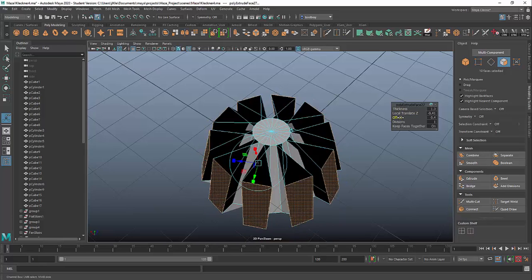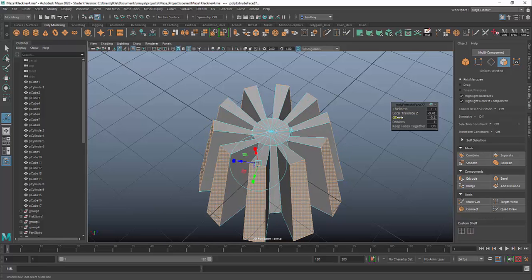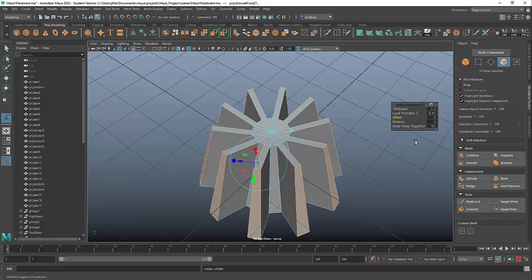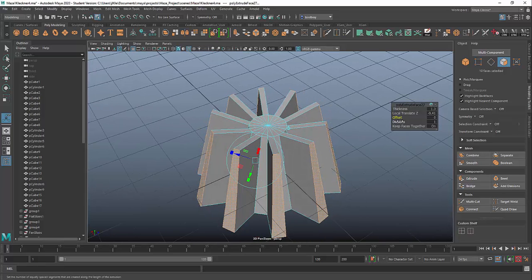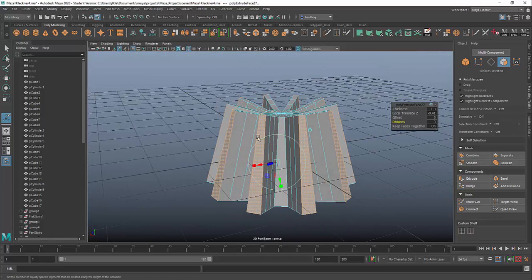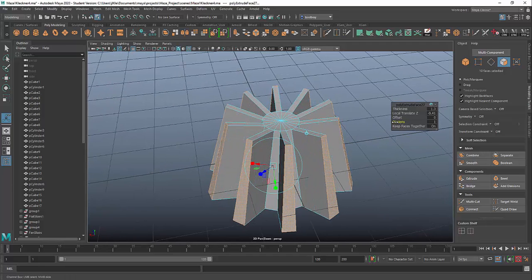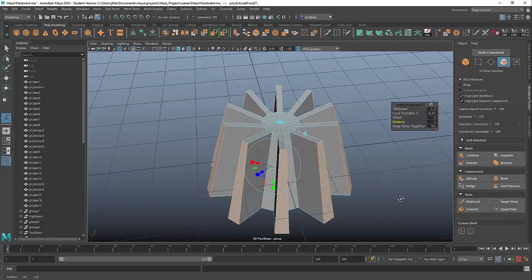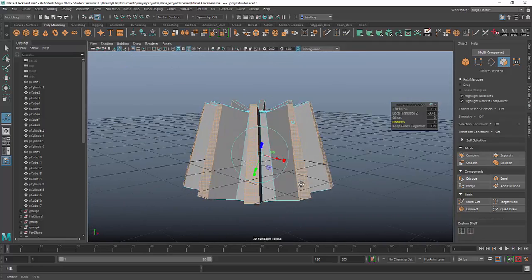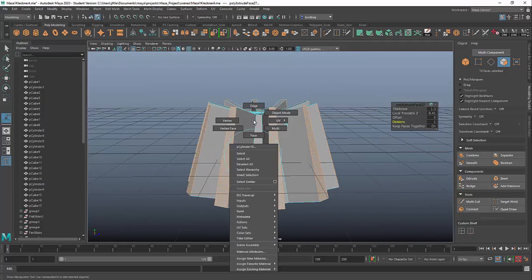If you're doing offset, it does something else. It's scaling in from here to here, essentially. So that's what's happening there. And then divisions. If I add some divisions, that lets me select smaller faces in between here. So you can see tons of options just from a single click. I'm going to leave it with no divisions there. And it's pretty amazing, right?